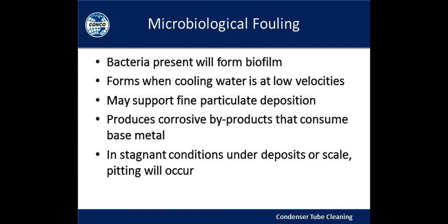But this biofilm, or this bacteria, may also be corrosive for the tube material. Many of you have performed non-destructive testing, or you have seen microbiological deposits that actually eat through the tube wall. They burrow into the tube, and they ultimately cause tube failure. Again, keep the tube surface clean.